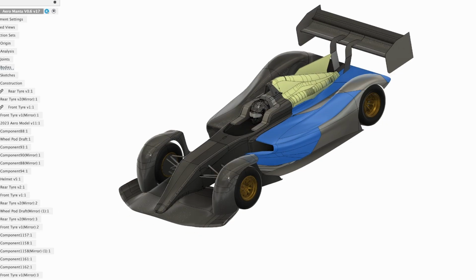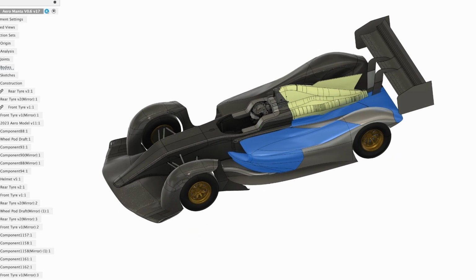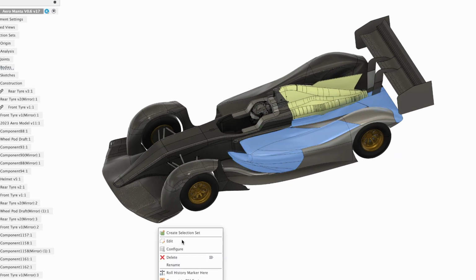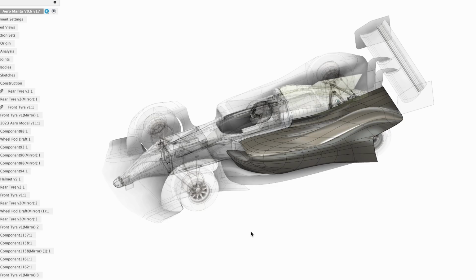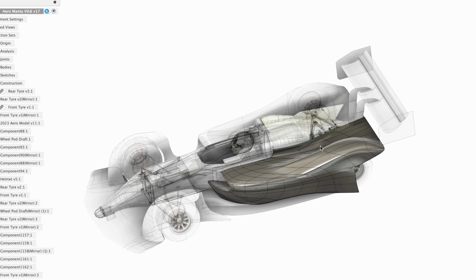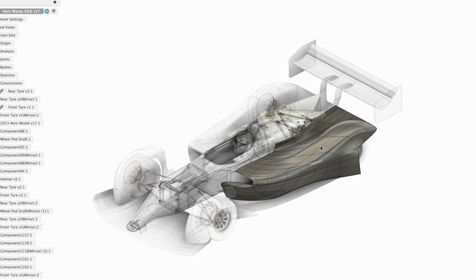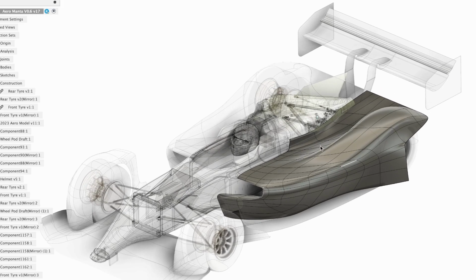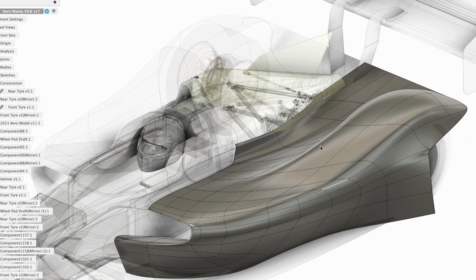One of the neat things I wanted to show you is actually how I go about creating these models and how that goes into Airshaper. So Airshaper is pretty neat in that it will take essentially 2D surfaces and run them in the software. Most CFD packages require a volume to do that.